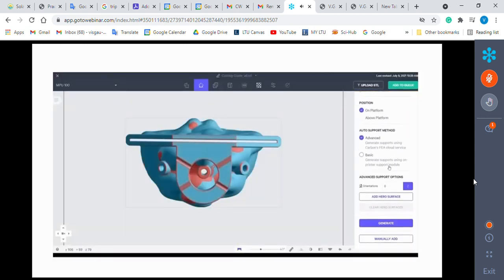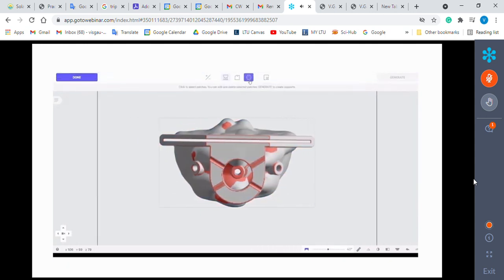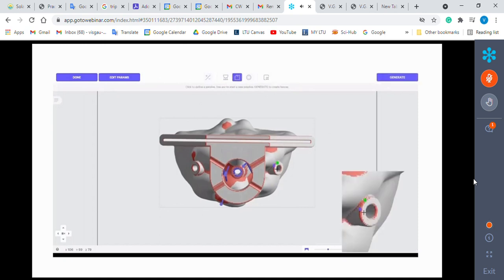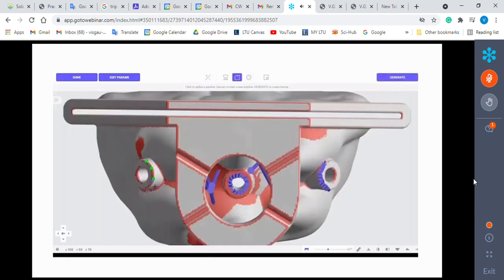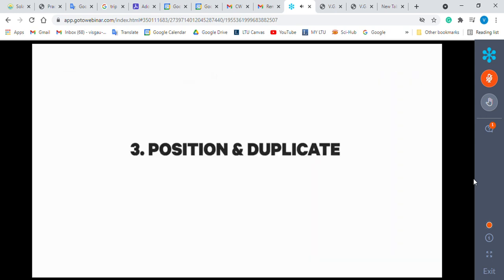And the next step is to add supports. So I'm going into our supports tool and selecting patch supports. So I can apply bar supports to a selected overhang area and generating those supports. And now I'm selecting a different overhang and I'm using the boundary fence feature in that patch supports tool and generating a boundary fence. And finally, I'm using our fence supports tool and I'm adding fence supports to 2 additional features and then generating those supports. And now our supports are complete.